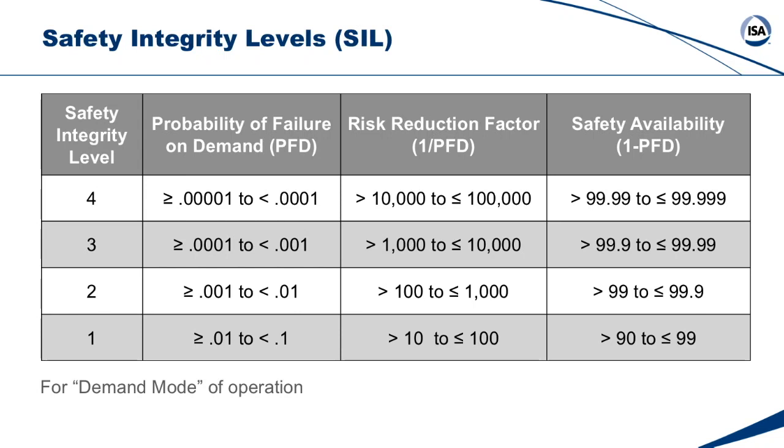And I ask them, write down 1, 2, 3, or 4, depending upon what integrity level you think that number falls in the PFD range, 0.005. Go ahead and mentally do that for a second. And in the 1996 version of the standard, we had the complement, 1 minus that. We called it then the safety availability, which was not a good term, and that term no longer exists. With that one, you just end up with this endless stream of 9s, which most people don't relate to either.